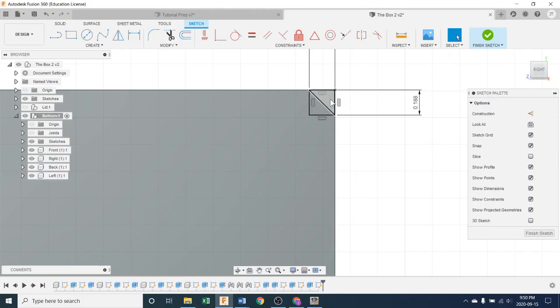Now, we can do a couple things here. We could leave it as is and just extrude that and ignore that. The other thing you could do is delete these lines using your scissors, which is probably what I would do to clean things up. The last thing you could do is turn those to ignored lines by clicking on them and pushing X, and that turns them into a construction line and they're not paid attention to anymore. Maybe I'll leave it like that. So X on the keyboard. The other place to get the construction line command is here.